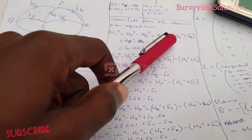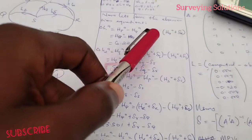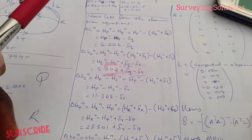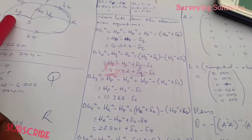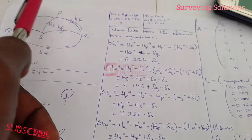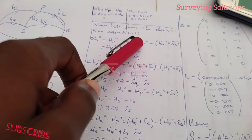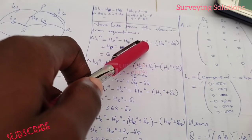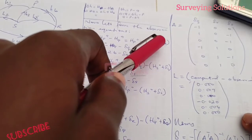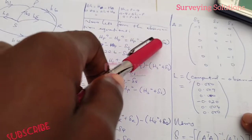Remember that P does not have any error because it's a benchmark, minus the height of Q observed plus the error in Q. Remember that Q is not a benchmark, therefore it has error, but P is a benchmark, so it will not have any error in this expression. Are we together? But Q, since it's not a benchmark, it's one of the heights we want to determine its most probable value, therefore it has this error. So plus the error in Q.